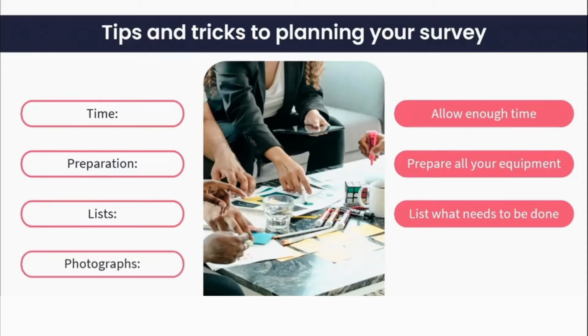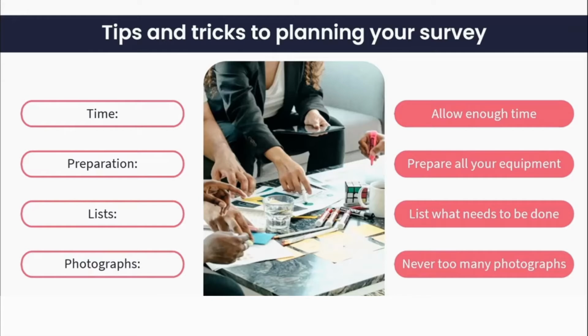Next, you want to take photographs. Photographs are never enough. You never have too many photographs. Make sure that you photograph every single detail of that site, as well as take full image shots. So try to get images showing the bigger picture as well as the smaller detailed elements. Remember, when you're back at your desk, you're going to rely on these images heavily. So you don't want to have to go back to site because you've forgotten to take enough detailed images or detailed visuals of the space.